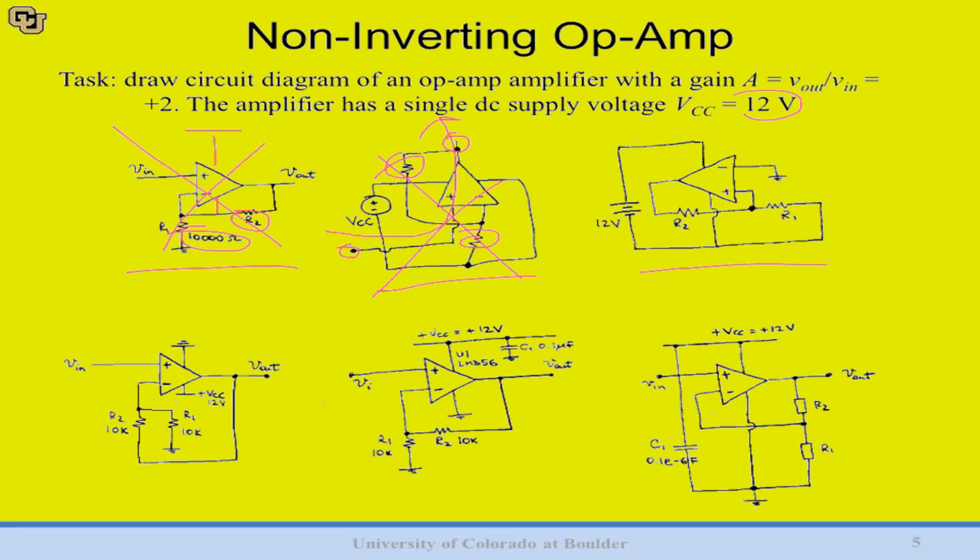This third attempt over here is again very confusing. When you just look at the circuit immediately, it's not clear where the input and where the output are. Turns out this is the input and this is the output, but it's not readily clear just by glancing at it. We also don't have component values for our resistors, as well as the fact that if we follow the data flow, we're kind of going from the middle to the left. That's non-standard, very confusing. We don't like this at all.